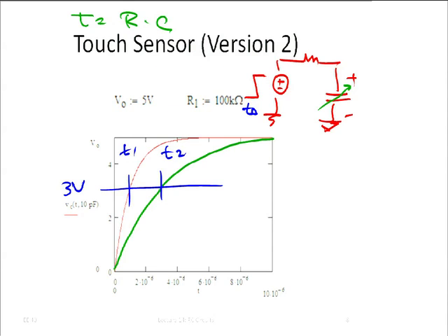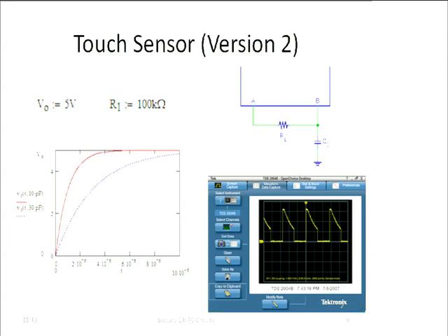And actually, this one works a little bit differently. It actually works by first, I write here, first we charge this thing up all the way to 3 volts, and then we are going to discharge it through the resistor R1. This actually is an exponential. That's a nice scope. We're going to discharge it to 1 volt or so. When we reach the 1 volt, we turn off a timer in our microcontroller.